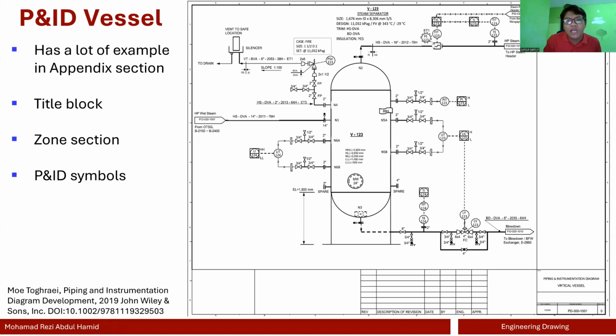Right, so let's begin. As you can see here, this is the P&ID of a pressure vessel. So what do we have? First of all, this P&ID is drawn on a drawing layout, and this drawing layout has a title block. This is the title block, by the way. A title block is basically a standard block where you provide non-graphic information like the company name, maybe the size, scale, notes, P&ID number, drawing number, maybe revision numbers and stuff like that.